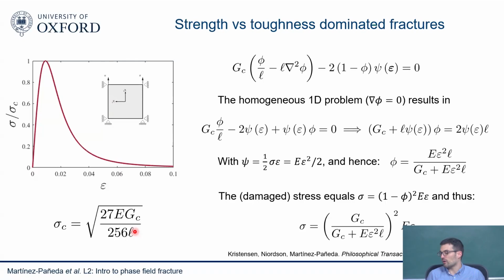But in principle, you could have materials with very small fracture size, like in glass you don't see anything and then you see complete failure. Metals are a bit longer. In concrete, you may get a more spread distribution of the damage. So that will give you the strength as well, basically. It will be connected to the strength.